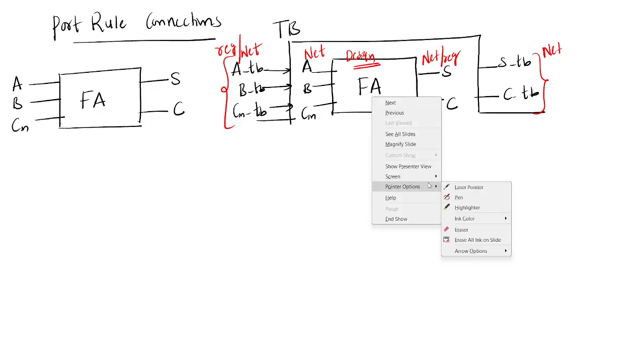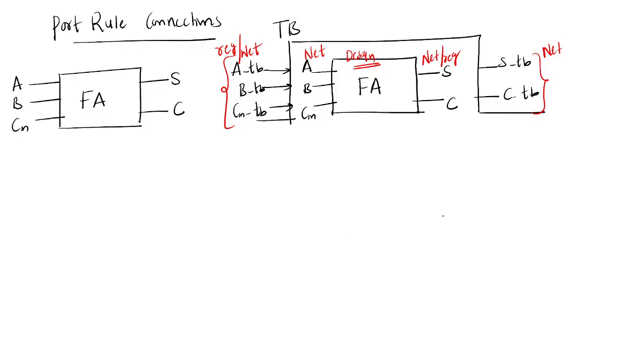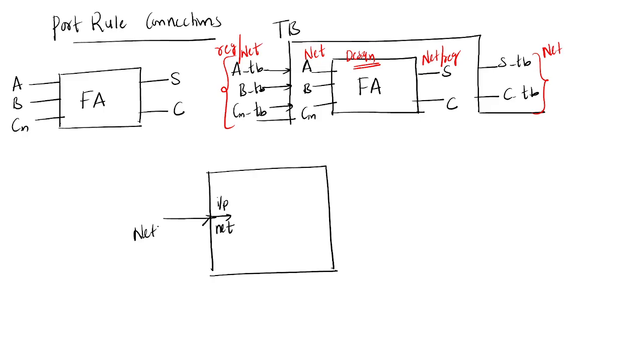Normally when you are doing a top level module, these rules we need to follow. In general, consider this is my design. The inputs for the design, the ports, we need to declare with net data type. And coming from the instances, it can be net or reg data type.